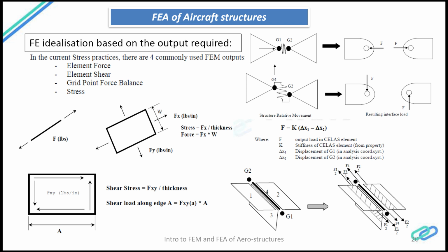And next one is the typical skin panel element, which is a plate element, which takes axial loads and could also take bending. It takes bidirectional axial loads. And this is a shear element, or the typical shell element, which takes only the shear force. It doesn't take any other force. It reacts only the in-plane shear.